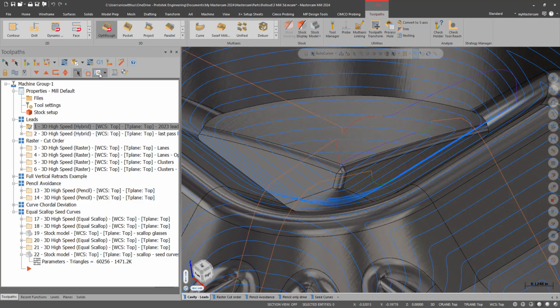I'd just like to point out too here, I have the advanced display turned on, otherwise everything's blue and yellow. I really like the advanced display. It was one of those quality of life enhancements several versions ago. I pretty much always have that on. The lead-ins are green and the exits are red, transitions are purple. It really helps me identify why that move is going there. Well, if I see what color it is, it gives me more information. I better know what to go fix.